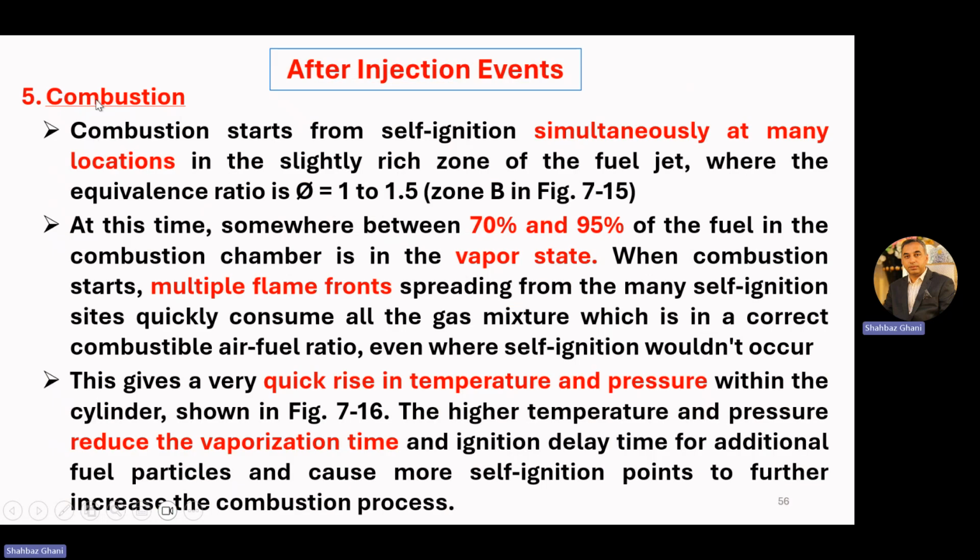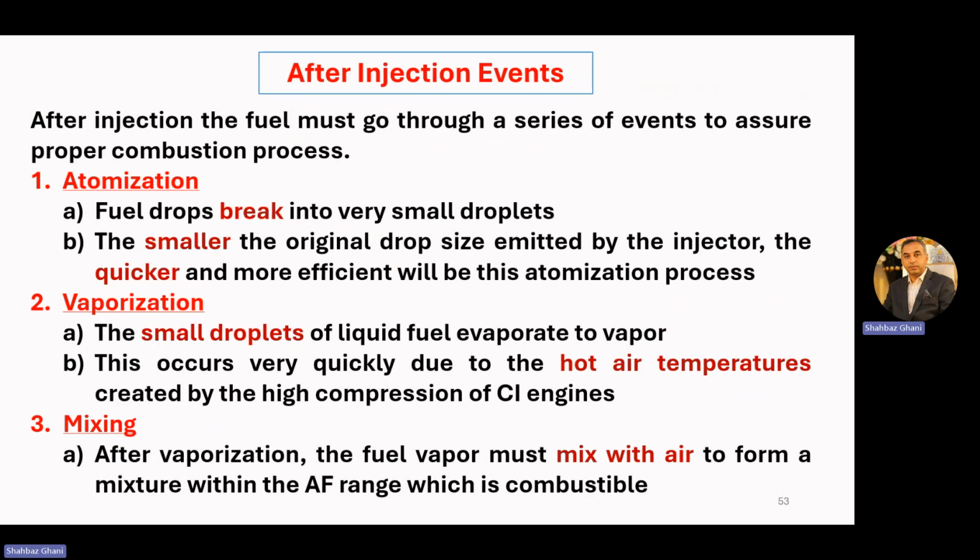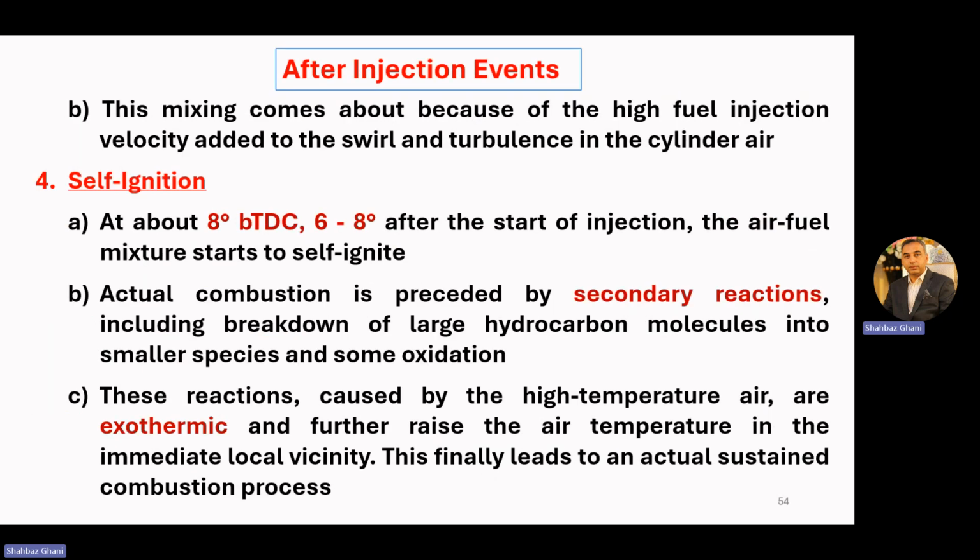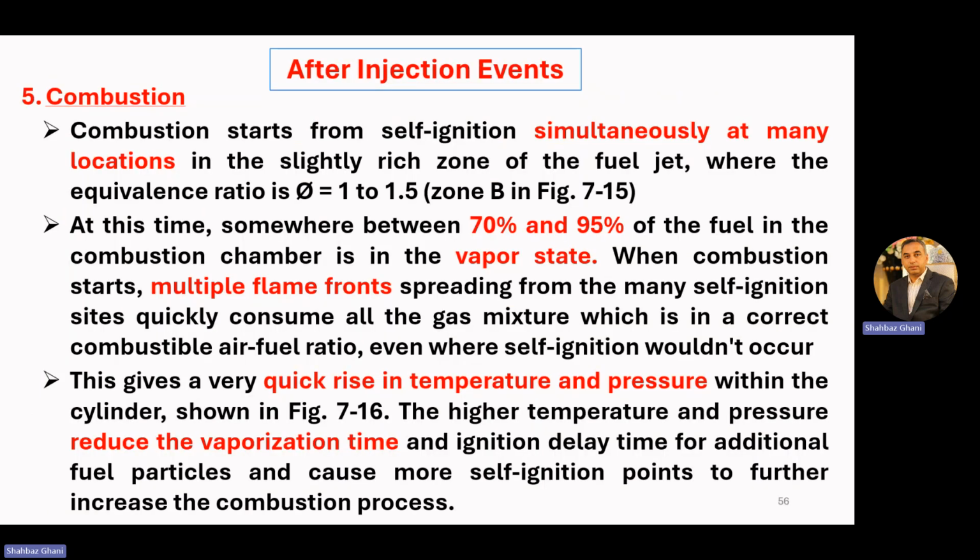Now combustion. First was the atomization, then vaporization, then mixing, then self-ignition. Now combustion. Combustion starts from self-ignition in zone B, simultaneously at many locations.